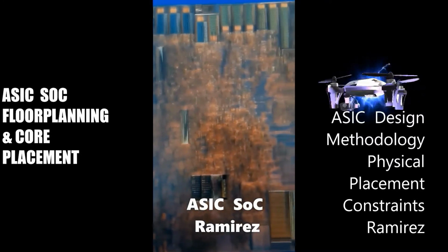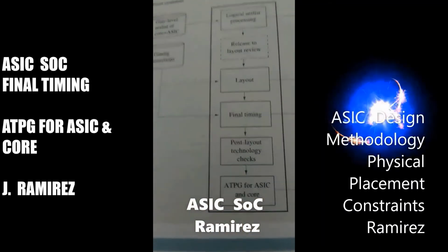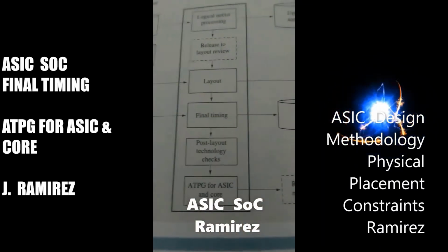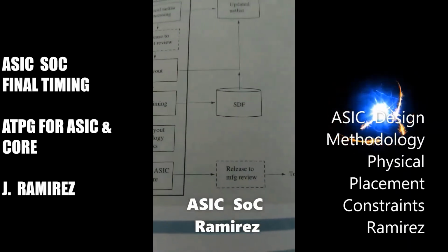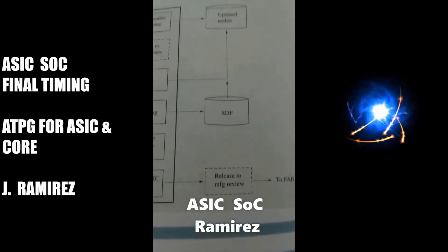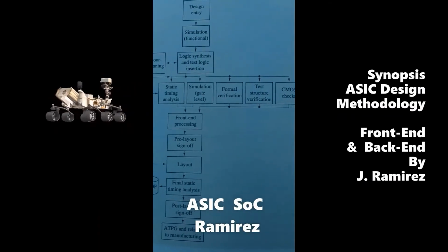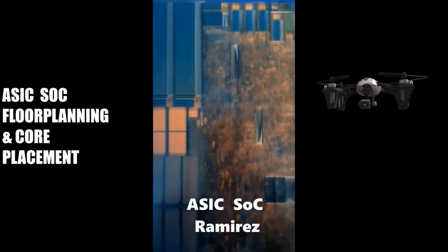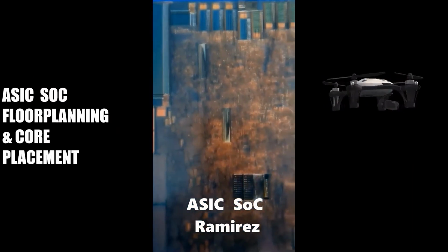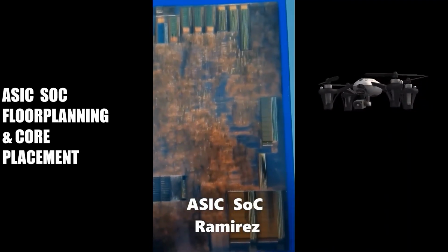Placement constraints. The area planner analyzes the distribution of the shapes and sizes of the library cells that take place in each macro cell and determines an optimal periodicity of circuit rows or columns and creates the placement structures based on each macro cell.